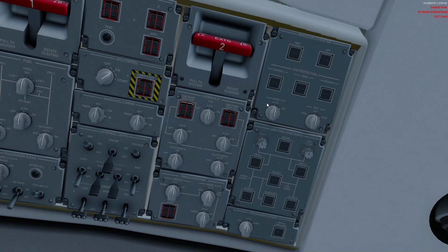So for example, if the mode would be turned on and I would push out wing, we would basically turn on the engine 1 and 2 anti-ice, but not the wing, because it would be forced out. So back to the original point, during pre-flight checks, we made sure that the mode switch is in auto.